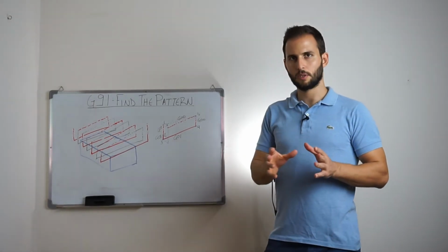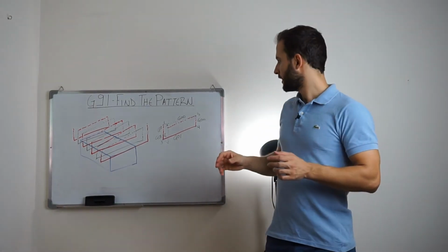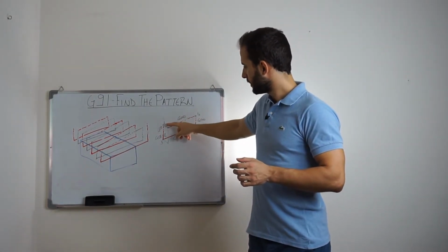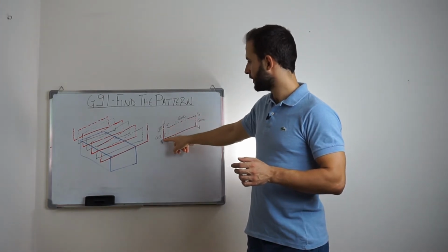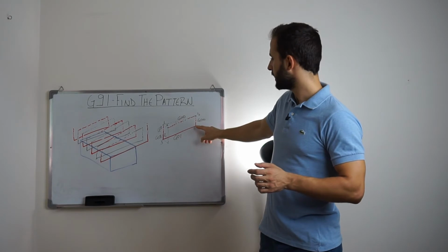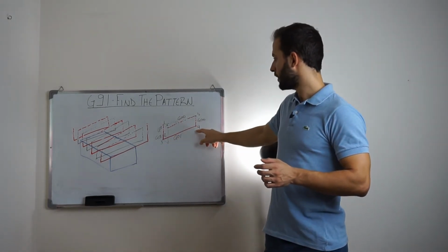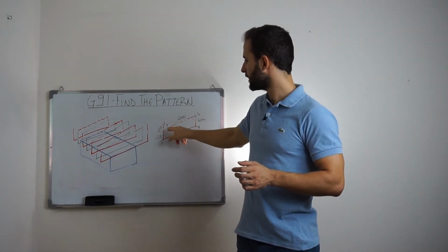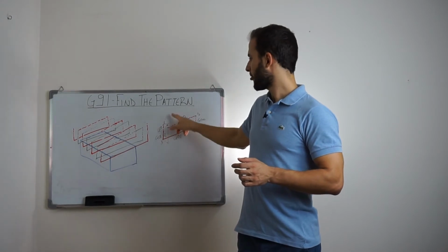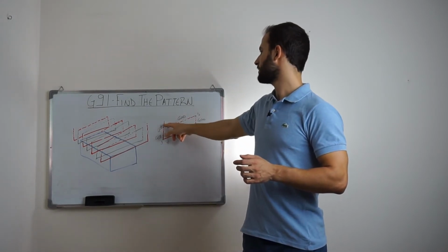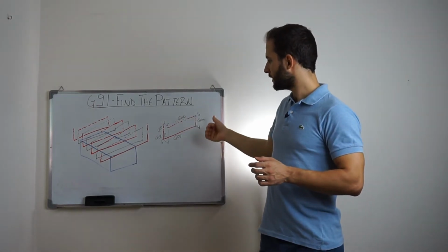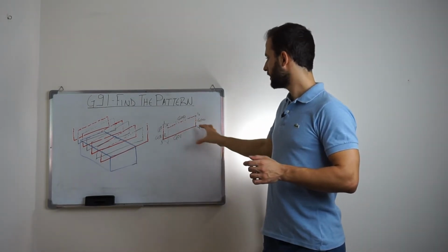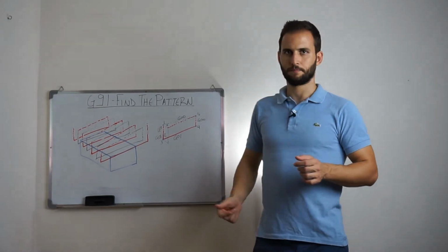So there is a basic block that can be programmed in order to automate this process. This is this one. We have a motion from point 1 to point 2, then to point 3 along the z-axis. We go along the x-axis from point 3 to point 4. We go up from point 4 to point 5 along the z-axis, and then we go to point 6, which has the same x coordinate as point 1, but is forward along the y-axis in order to take the second pass. And then the same blocks are repeated in order to complete the face milling process.